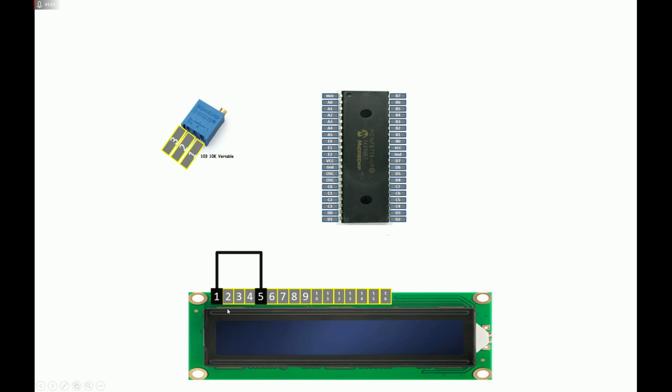Connect pin number 1 and 5 of the LCD like this. Then connect it to the pin number 1 of your potentiometer. Then you send it to the common ground of your PIC like this. In this way, your PIC gets the ground, your LCD gets the ground, and your potentiometer gets the ground from the same source, which is powering up the PIC. Like in my case, I will be using the PICkit 3. So PICkit 3 will be enough. It will be able to supply enough current to power all 3 components. So that will be fine.